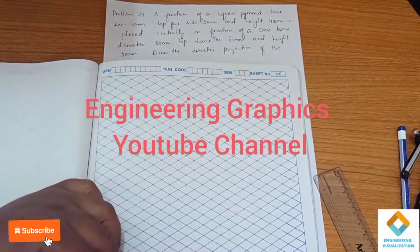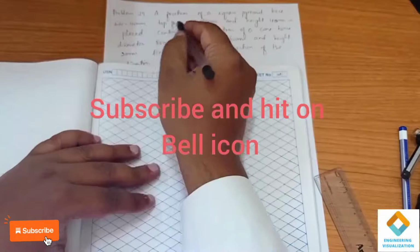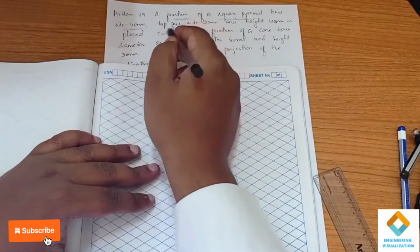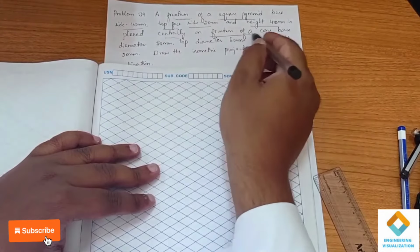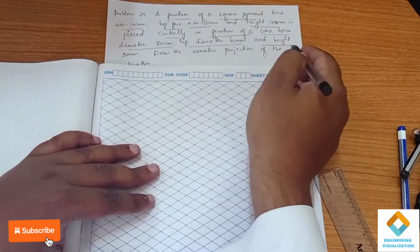Problem number 39 from the CAD solution book. A frustum of a square pyramid, base 40 mm, top face 20 mm and height 40 mm, is placed centrally on a frustum of a cone with base diameter 80 mm, top diameter 60 mm and height 20 mm. Draw the isometric projection.